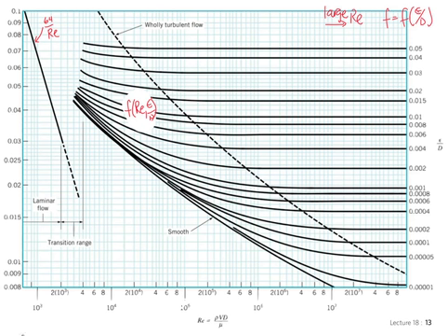And also we note that there's a transition range where we don't know F really, because in the transition range the fluid can behave as laminar or turbulent intermittently, and so we really can't tell. In that area the values are not known. They're indeterminate. So no values are given for what should be the transition range, between 2000 and 4000, that's the transition range in pipe flow.